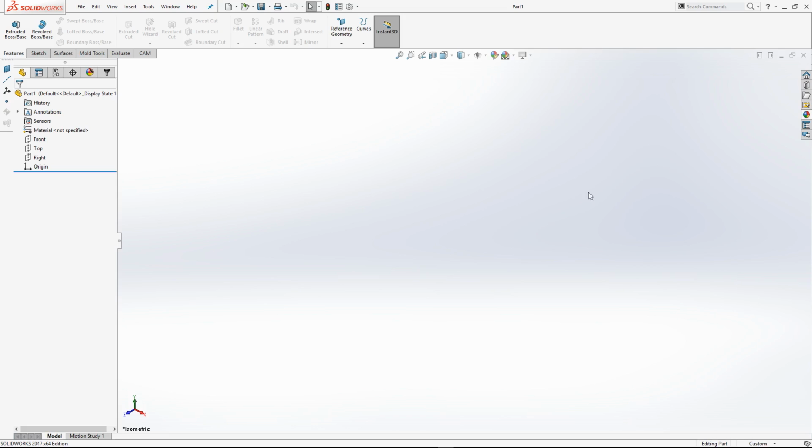The library, which is this section here, contains some predefined functions or standard components. If you design a bolt that you know you're going to use in designs down the line, you can save that as a default component, create a library and put that bolt there, so you can just drag and drop it in.